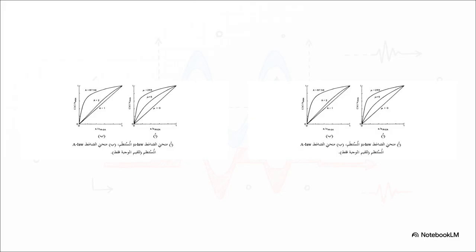And these curves show you exactly how we do it. These are standard compression laws. Mu law is used in North America, A law in Europe, that define these non-uniform levels. Look how steep the curve is right there in the middle. That means a huge range of quiet input signals get mapped to many, many different output levels, which preserves all that subtle detail. Then as the signal gets louder, the curve flattens out, dedicating fewer levels to the loud parts. It's a system that's literally tuned to how humans hear.